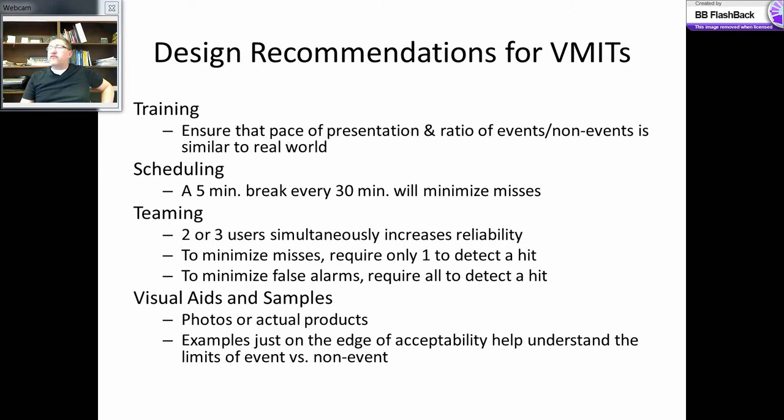If 3 sensors all individually say we're detecting this signal, then there must be a collision around those 3 sensors. Maybe it's a small enough collision that it doesn't activate the sensors on the other side of the bumper, but it's large enough here that we should act, and 3 of us agree that it's happening. We're not going to agree unless it's significant, and the probability of all 3 of them failing at the same time is very, very remote. So that redundancy means we have a lot smaller chance of a false alarm.